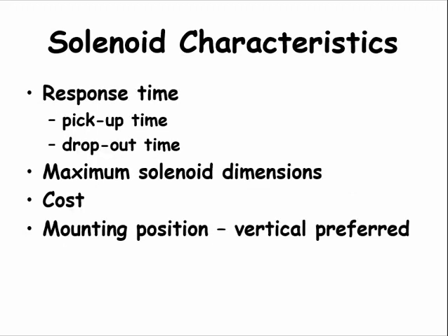Similar to the discussion about relays, solenoid response time when energizing, which is called the pickup time, and when de-energizing, the drop-out time, can be important in some processes. Other things to consider include the solenoid dimensions, cost, and mounting positions.